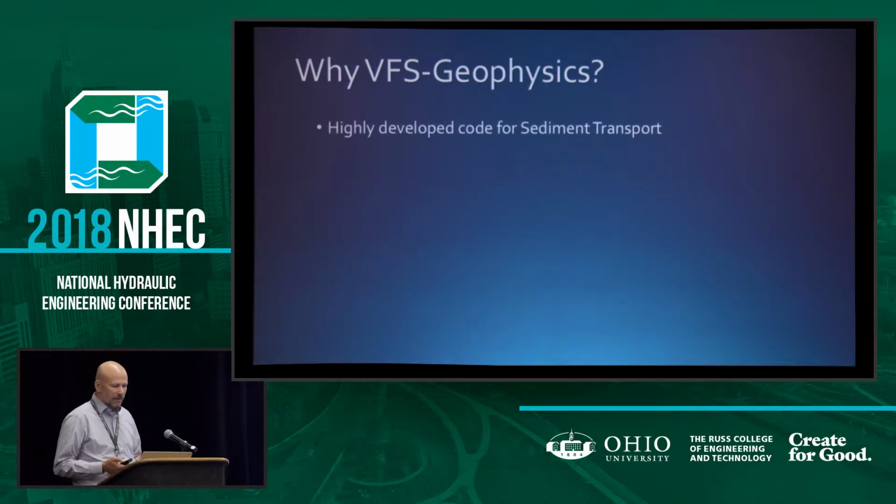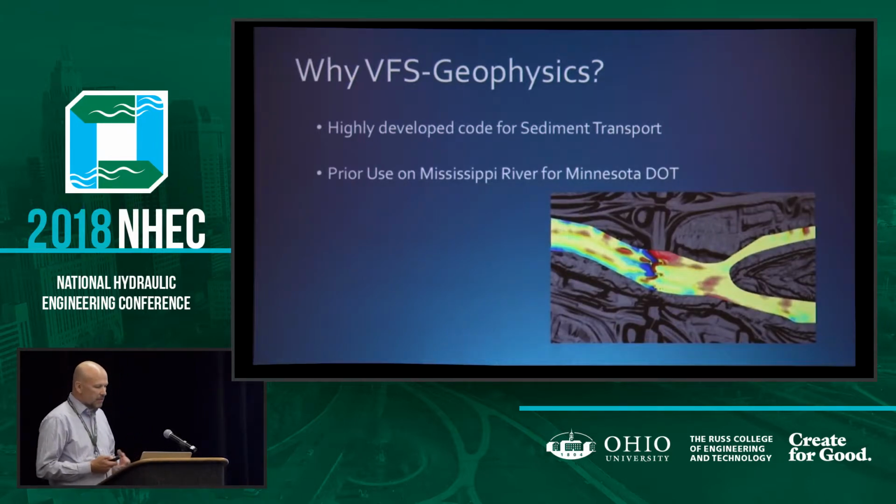What was attractive about VFS Geophysics? Well, they've spent a lot of time working on the sediment transport piece. OpenFOAM, those types of codes are very general, and there are people developing pieces to do scour, but I don't think it's quite up to the same level of effort or refinement that VFS Geophysics has. They had used it prior with the Minnesota DOT on the Mississippi River. They modeled a massive stretch of river using LES, which is a very advanced form of turbulence modeling, and it seemed to model the scour. So I was very impressed with what they had done.